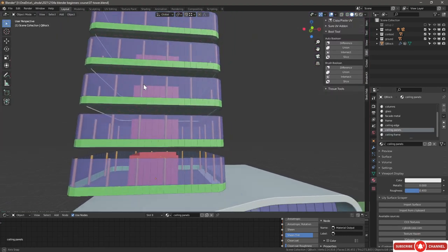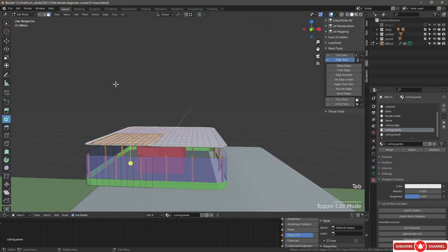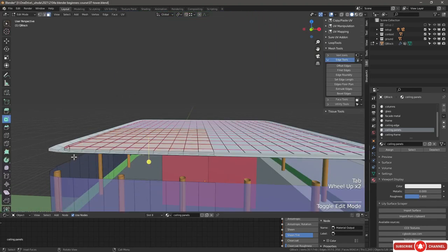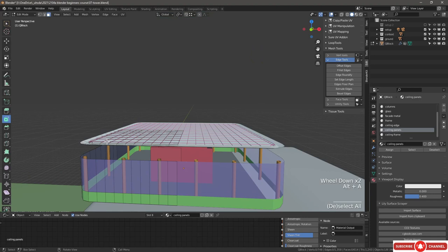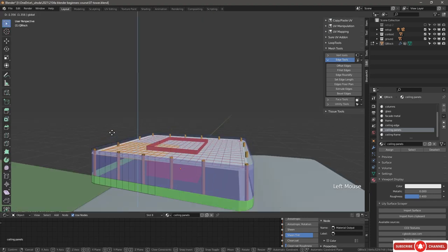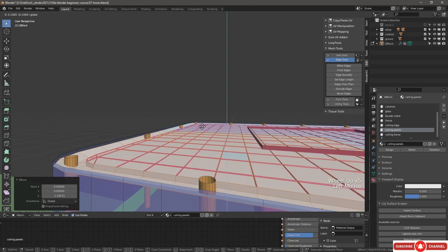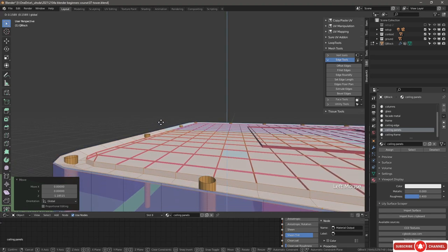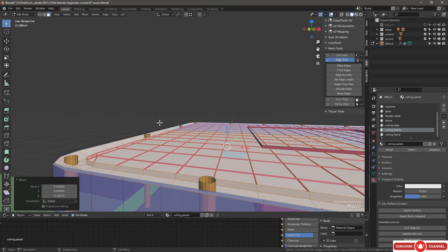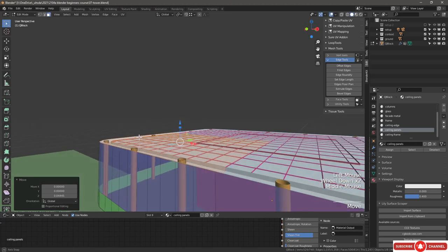And as you can see, our object has a mysterious gap in the building and it's magically hovering. And the reason for that is because all of this is hovering. So let's select everything, L, and now let's move it down to somewhere over here. And what we need to do with the snaps, they're a bit finicky the way they work, but if we get one of these vertices to be the closest, if we try it now and hold Control, it should snap to the appropriate one.